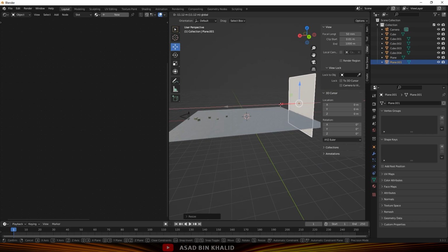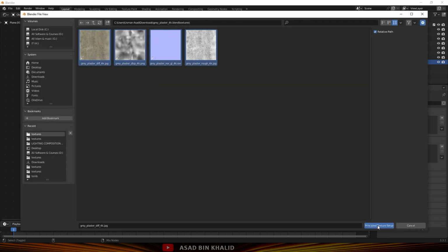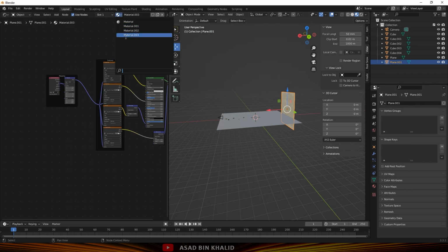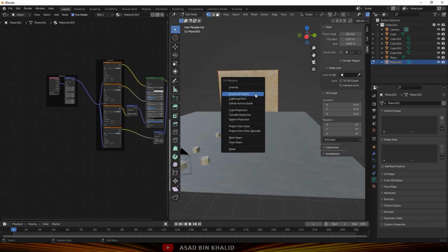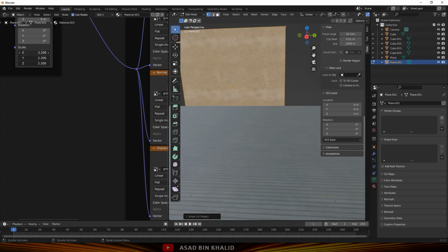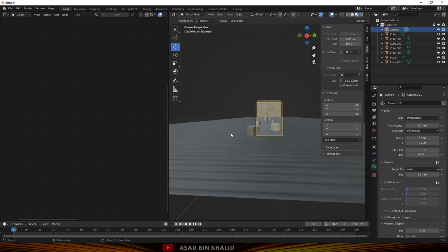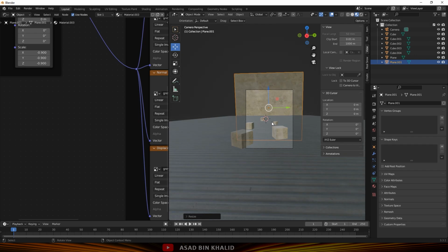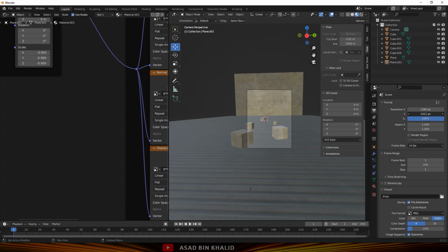You can give any kind of texture back. So I just give it partial, some kind of poster, because I want to make it very simple. You see, again copy. You can just use the same material, but this is my way. So yeah, again press Tab, select all, UV unwrap, and this is perfect. Then adjust it according to the scale you want. Then go to object mode and press 0 for the camera view. One thing I don't like is that this is a little wide. So let's put it like this, good enough for my taste.